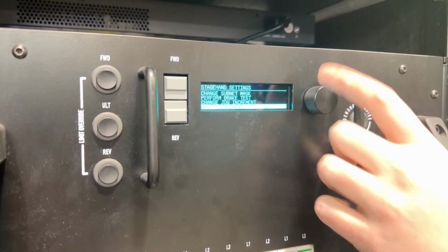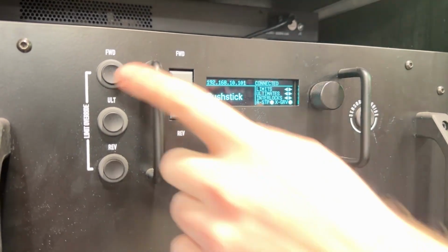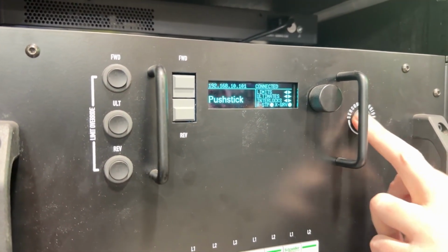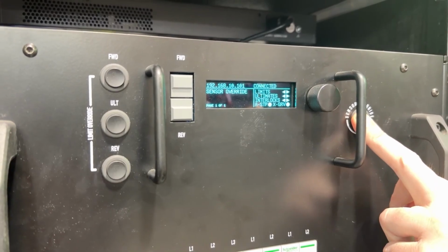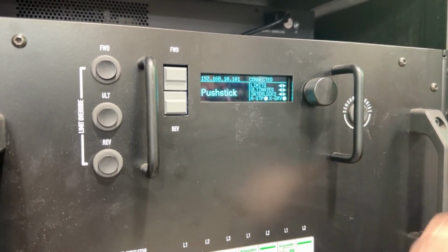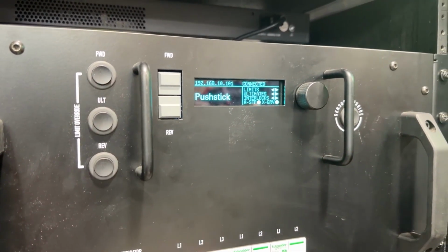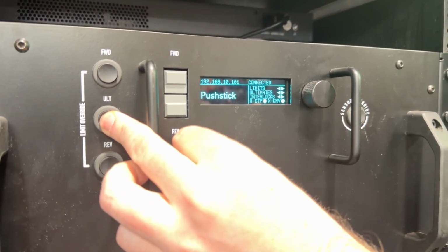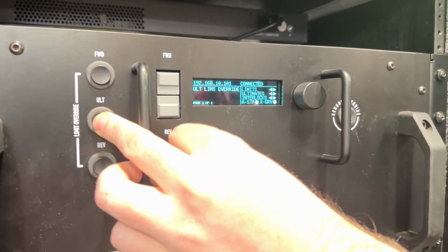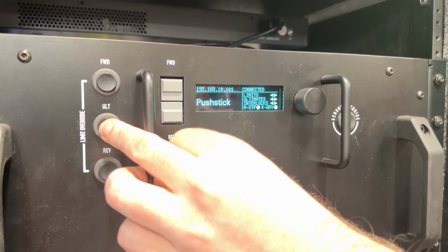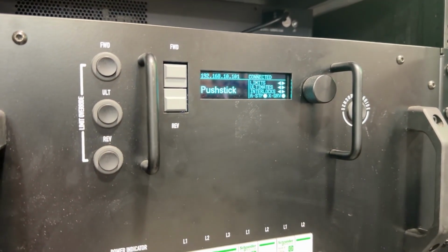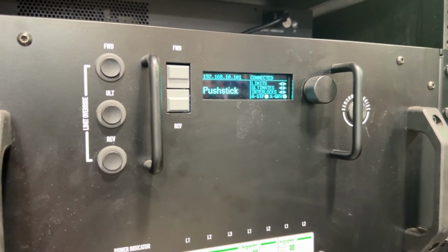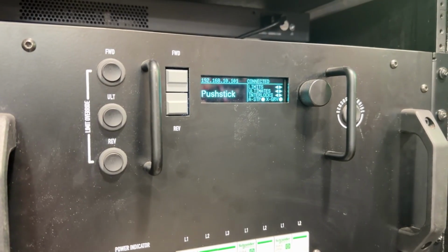Did you mention overrides? I didn't mention overrides, but I can. Yeah, so you get momentary overrides that you can use as you're bumping through and troubleshooting things. If you've run into a limit, say the alt limit, and you need to drive off of it, you can come up to the faceplate and override that locally. You have to be local to do these overrides, and you do get feedback at the console that something is overridden, like, hey, I should move that. Someone's overriding something.